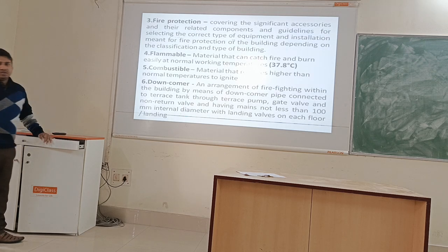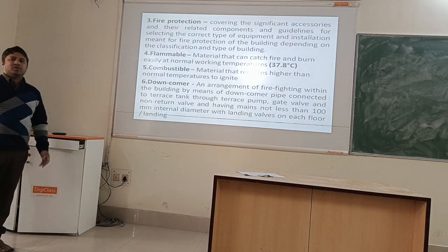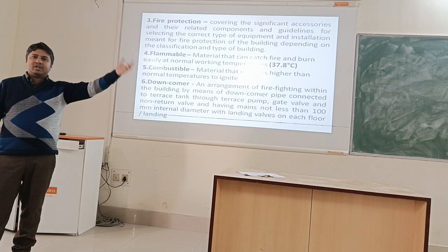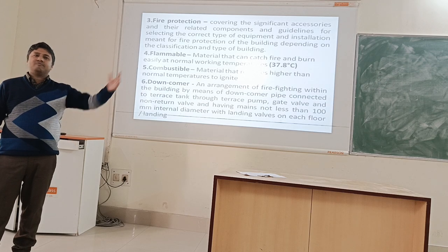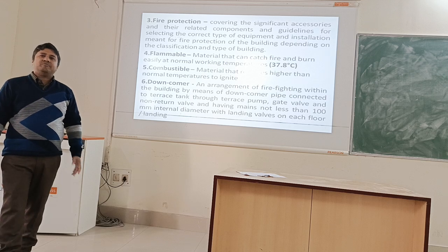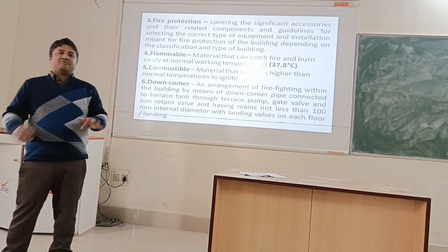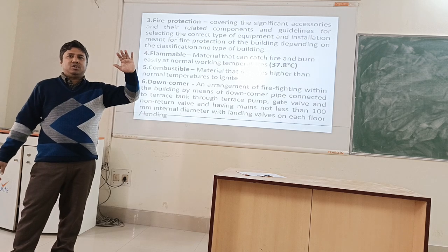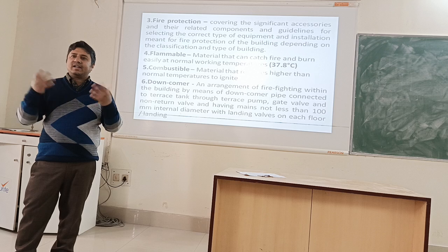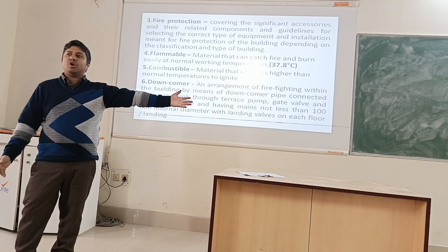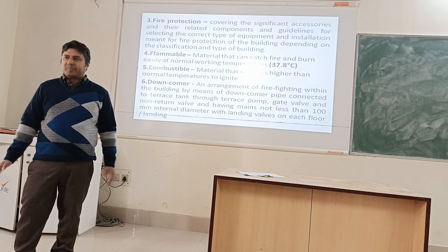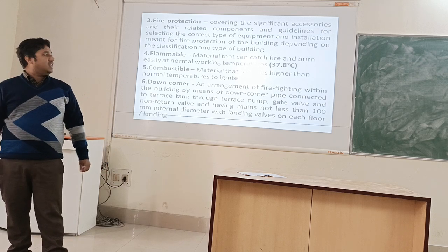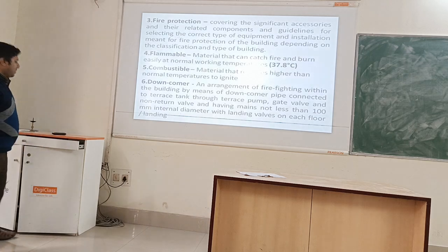Next is fire protection. Once the fire catches in a particular room, then with the presence of combustible material, it will transfer the fire from one room to another room. So if I have insulation provided in the floor, in the walls, in the roof, then if fire catches in one room, it will not pass to another room. All those measures present in the form of insulation in the flooring, in the walls, in the roof, fall under fire protection.